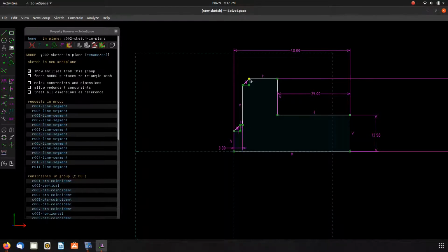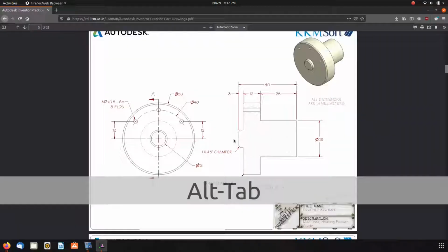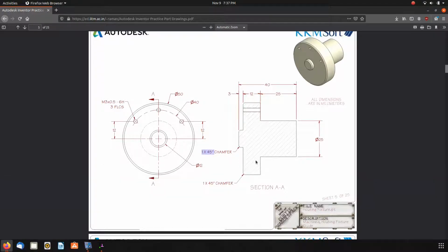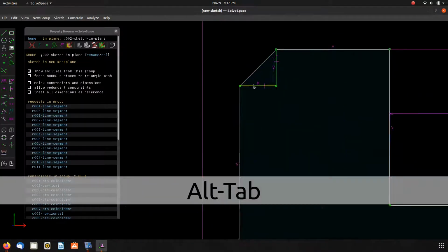So the chamfers are changing here, so I know that's 1 degree of freedom that I need to constrain. So I go and I find the chamfer callout. It's a 1 millimeter chamfer at 45 degrees. So those are the same. We established that earlier in the dimensioning. So I type in 1.0.